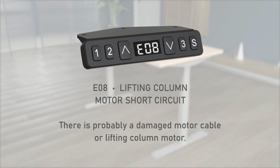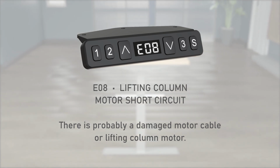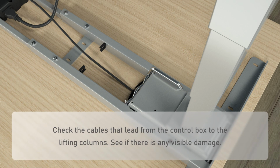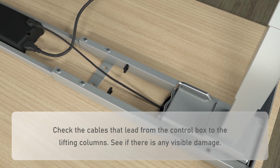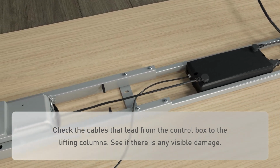E08, lifting column motor short circuit. There is probably a damaged motor cable or lifting column motor. Check the cables that lead from the control box to the lifting columns. See if there is any visible damage.